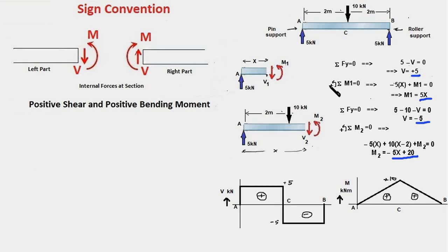And we stick to our usual sign conventions, that is, the forces pointing upwards are positive and anti-clockwise moments are positive. These sign conventions are up to us, but the sign convention of the bending moment and shear force is as per this sign convention, and we do not have any freedom to change this.